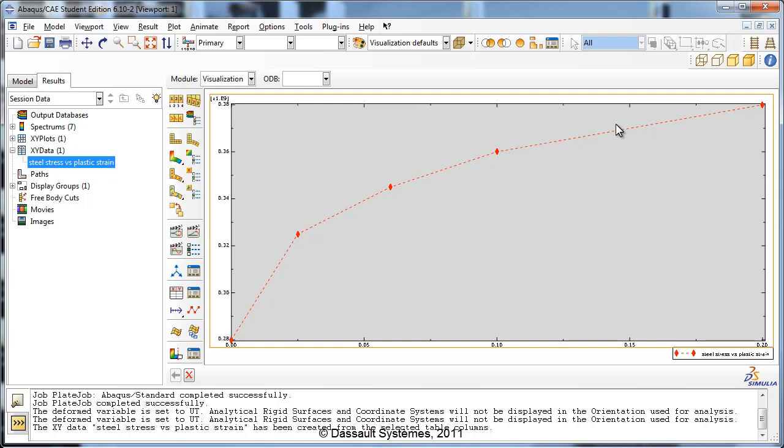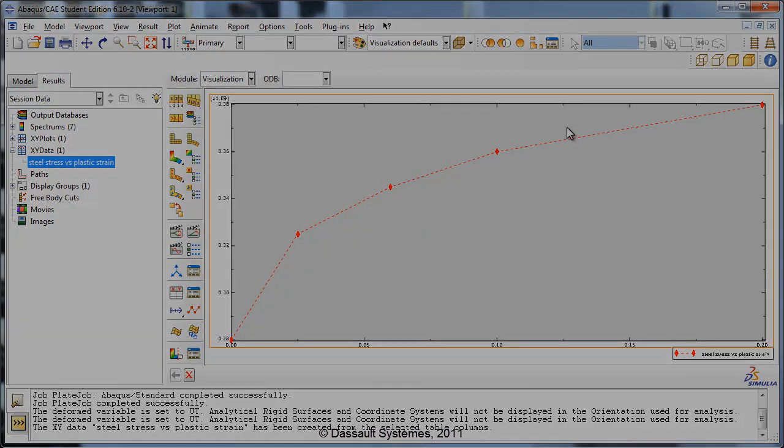In layman's terms, this means it will generate stress-strain data points that will form a nice smooth curve. However, it is possible that the points it generates may not coincide with the original user-supplied data points. Abaqus Explicit will attempt to generate a sufficient number of intervals so that the maximum error between the regularized and user-supplied data is less than 3%.